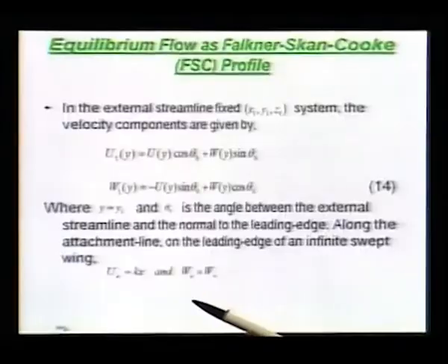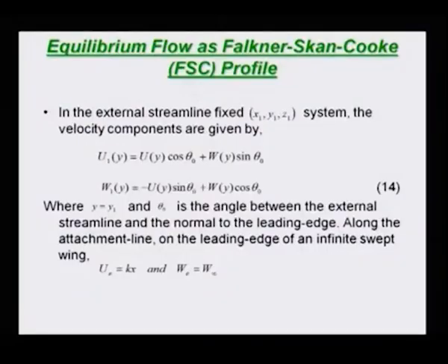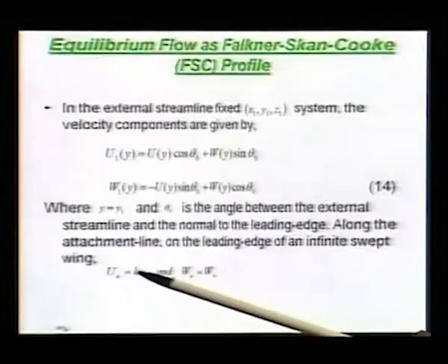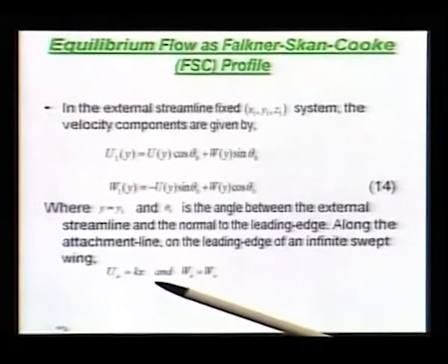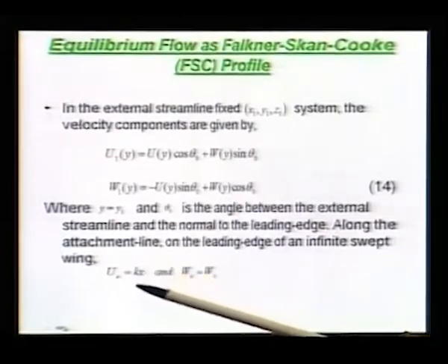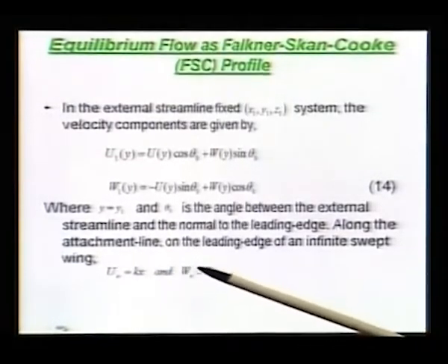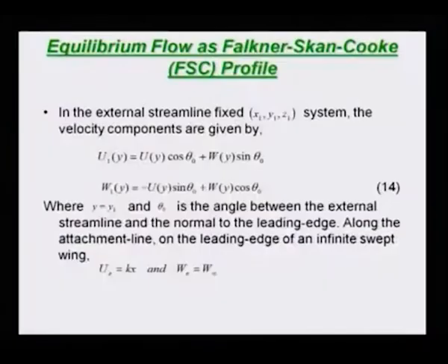But in this case, you don't have a y component there. So you have this, and this is directly proportional to the x component, whereas WE is equal to W infinity itself, because once you are outside, the flow does not change anymore. That's the definition of infinite swept condition, that WE will remain the same. There is no additional spanwise pressure gradient. That's the whole idea.